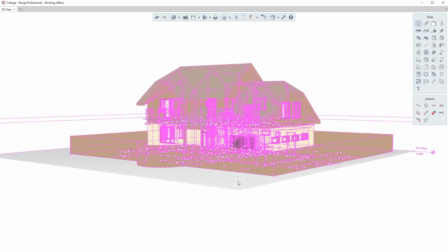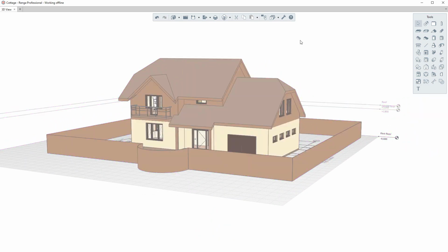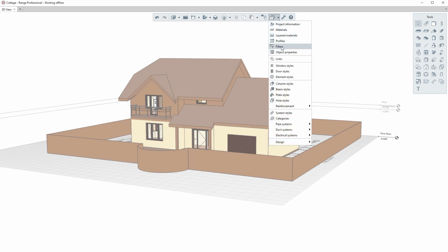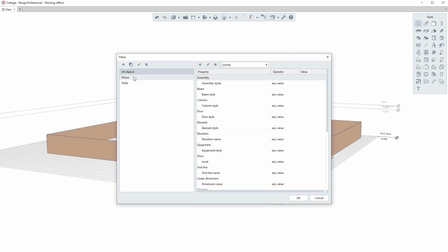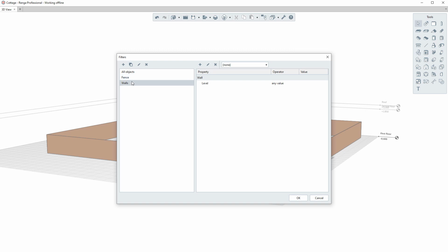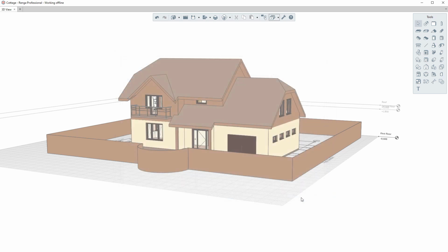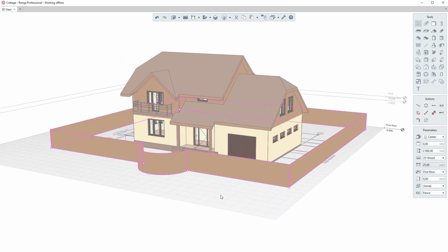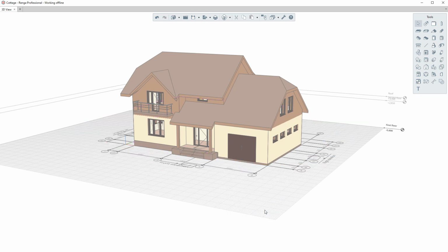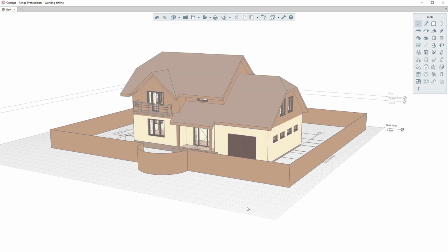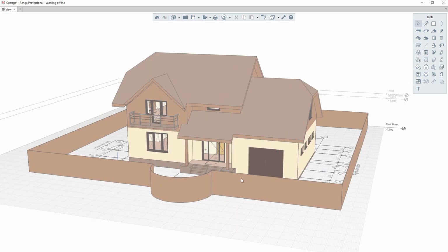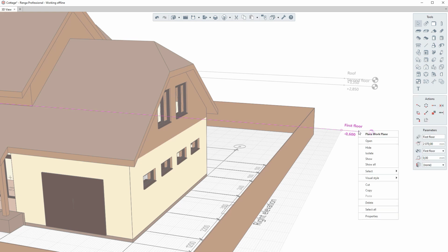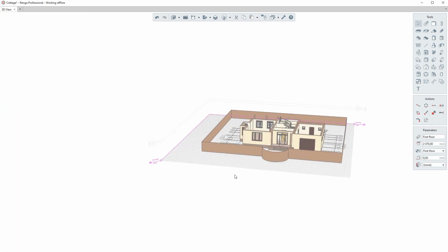It is very convenient to use the tool filters to select, hide or isolate model objects. Renga filters allow you to select only those model objects that match the specified criteria, for example, all the walls that belong to the fence. We can choose these walls, hide, or isolate them. We will go into detail about the filters tool in the following lessons. For the convenience of further work, we isolate the first floor.